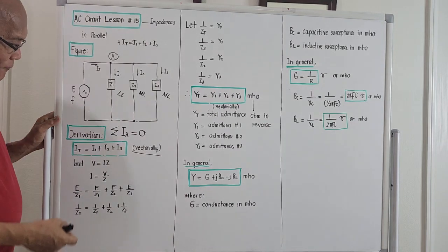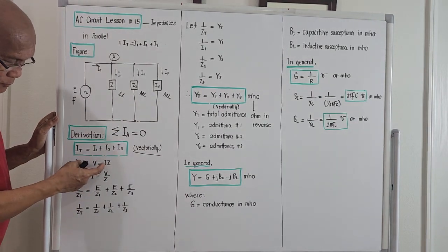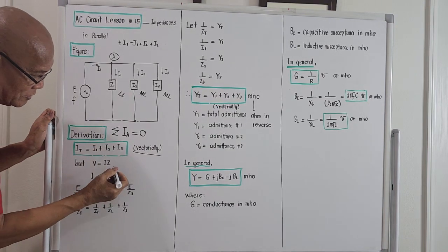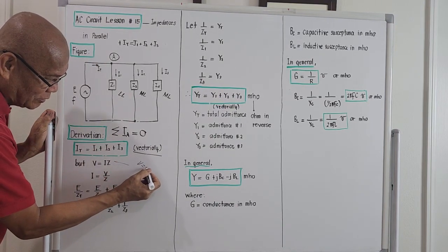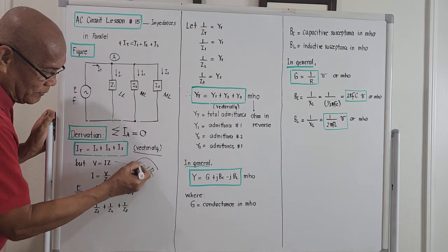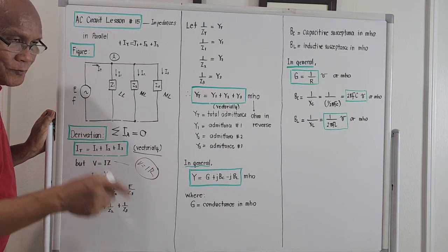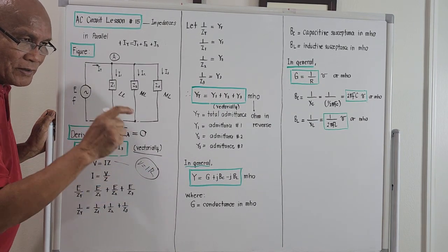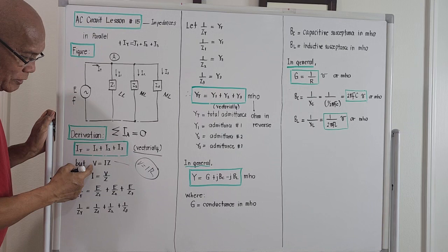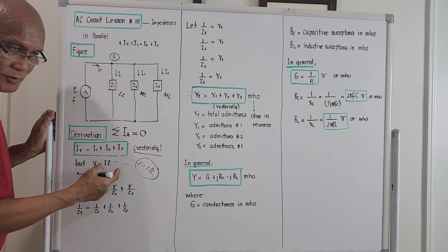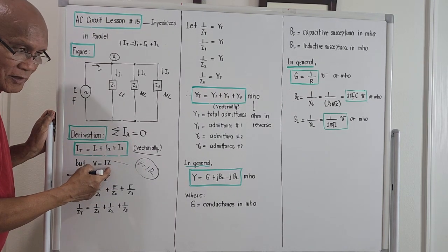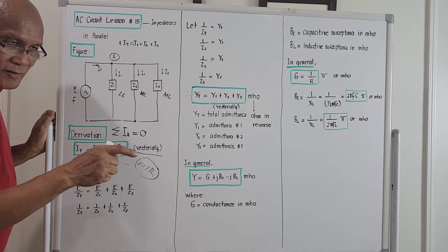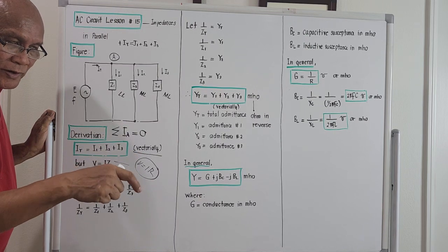By definition, voltage is equal to the product of current times impedance under an AC circuit. The equivalent of this under DC is voltage equal to IR, because the only opposition offered to the flow of direct current under a DC circuit is resistance. But under impedance, total voltage will be equal to the product of current times impedance, in which this impedance has the real part and the so-called imaginary part, and that is R plus jXL minus jXC.